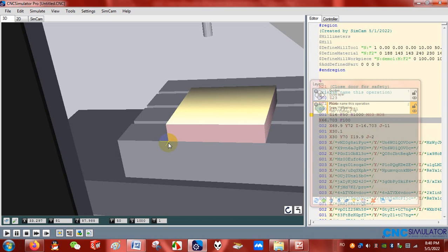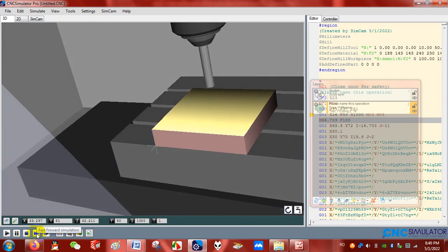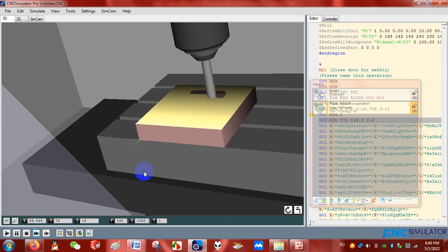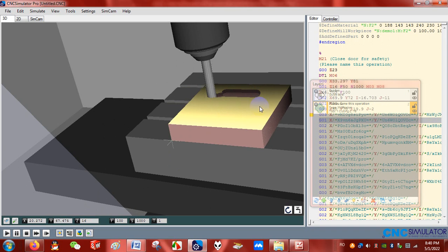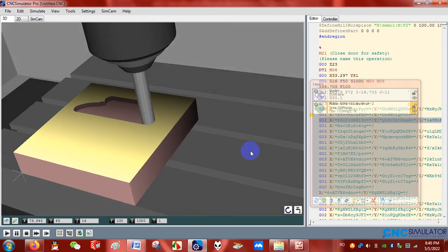If you want to modify this zero, we need to appeal to the G92 command. So if I want to put it in this corner, or in this corner, or in this corner, I will have to appeal to the G92 command. Okay? So I will fast forward this, and we shall see now the effects of our program.